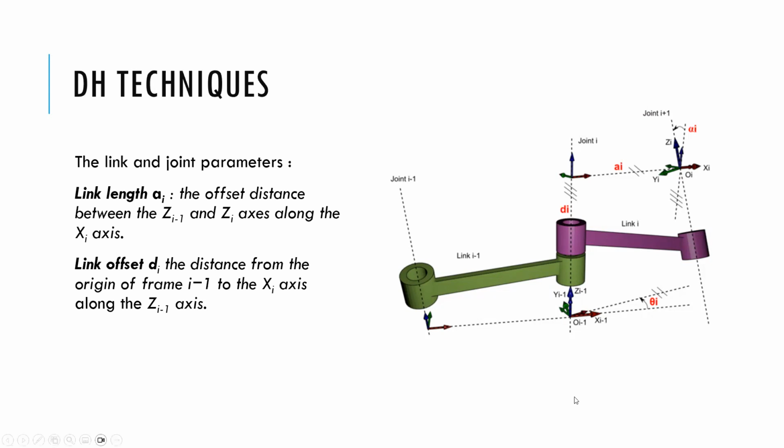They do this for every link. If I want to go from this link to this link, I could go through a series of rotations, translations, and rotation-translations. They extract these components: the d, the height offset; the a, the distance along the x-axis; the rotation about the x-axis, which is this alpha term; and this theta term, which is the rotation about z. They link these matrices together to return still a single 4x4 matrix. These are some of the definitions coming from their formulation.